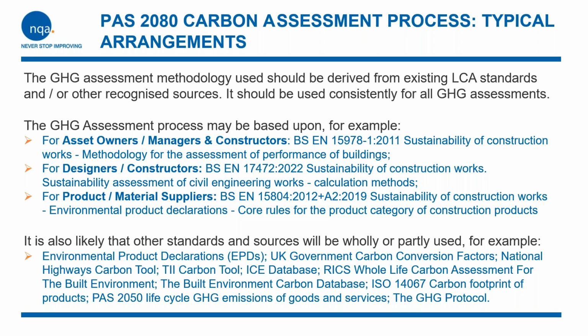And then you can play around with them, and you can actually change the type of material that you're using, and you can identify low carbon opportunities by using, for example, GGBS cement or fly ash containing concrete or HVO or biofuel or whatever it might be. And you can play around with those tools and they'll do the hard work for you in terms of the greenhouse gas assessment process. Clearly, those tools are intended for highways projects. You know, Transport Infrastructure Ireland and National Highways are primarily highways infrastructure organisations. But they're useful not just for highways projects, for any construction projects. Actually, it's possible to use them for those as well. It might not cover every angle, but it's a good starting point for learning how to do it.